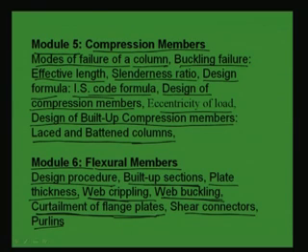The plates, additional plates, whatever we were using in the mid span where the maximum moment is developing, we can reduce step by step towards the support. If the support is simply supported, that means moment is going to be 0 at the simply supported end. So, how to find out all these things, we will discuss in this module.